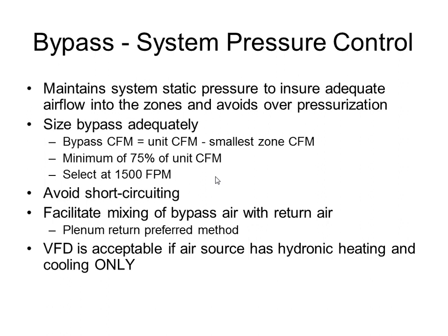And another part of short cycling is properly mixing the bypass air with the return air. We're going to look a little bit more into that on the next couple slides, but it's very important as well to prevent your supply air from getting too high or too low.